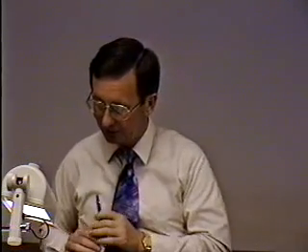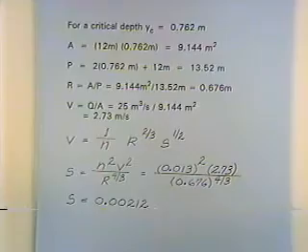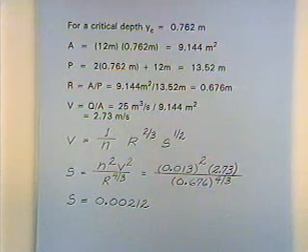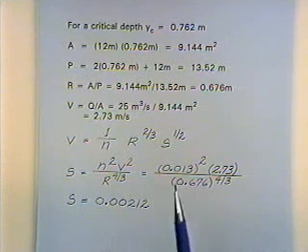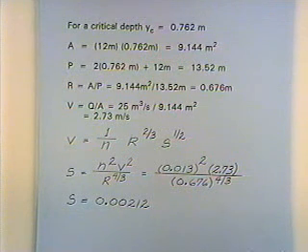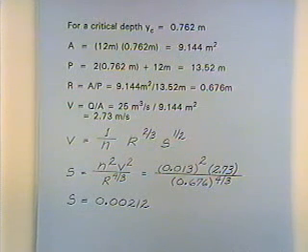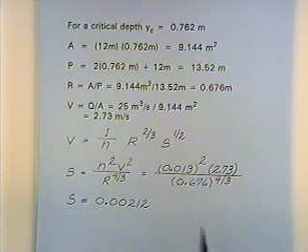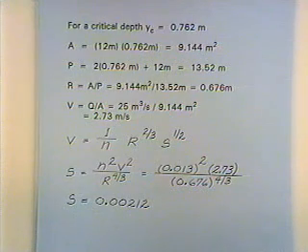And so the actual depth, we're assuming uniform flow, that there are no other irregularities. It's an otherwise prismatic channel, and so we'll use Manning's equation. And so what we've done, and again we could compute the depth upstream and downstream. What I've chosen to do, just because I'm lazy and I could eliminate one computation, instead of computing a depth upstream and a depth downstream, that's two numbers, I'm just computing one slope.